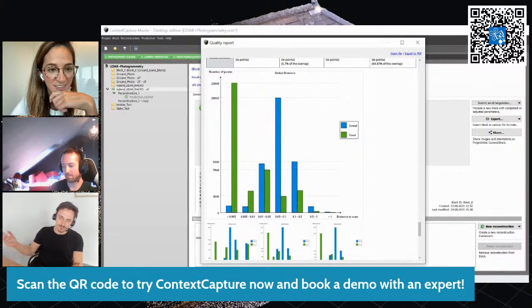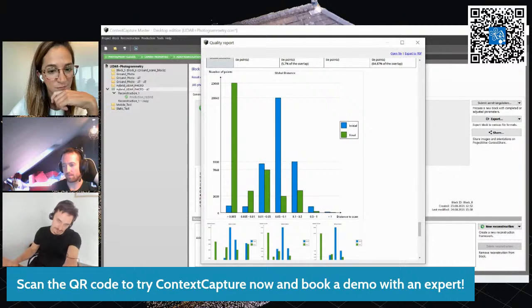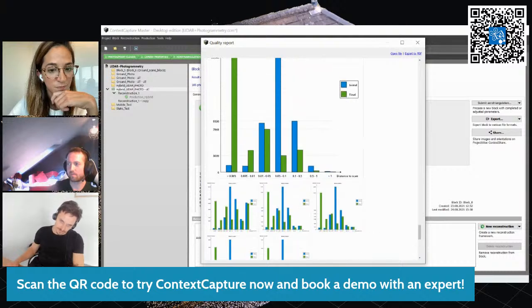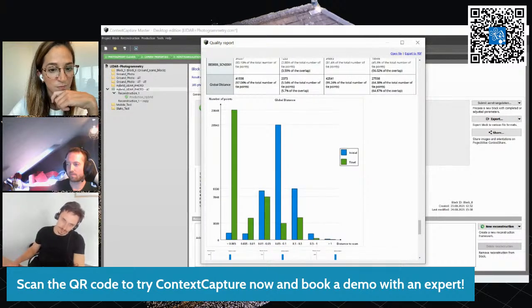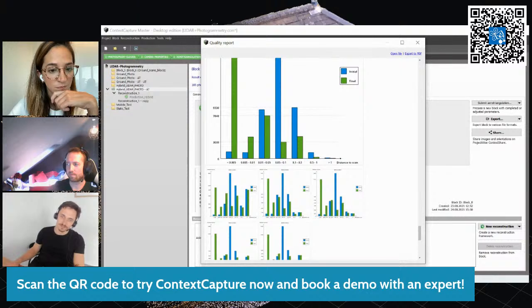But once you're using proper techniques with the ground control points, or in the case of point clouds, you will get charts, as you see here, that look like histograms, which show the number of points per distance to the scan. That is a statistical distribution of the distance and the quality of the overall fitting of the photogrammetry to the scan.